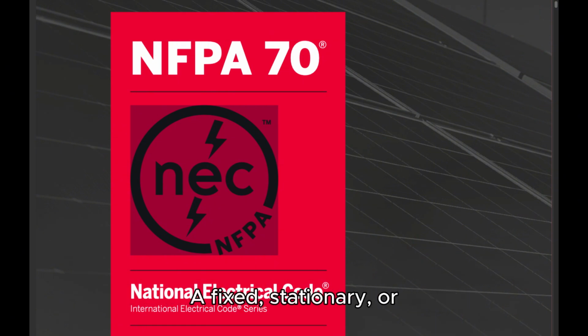CMP13 electric sign. A fixed, stationary, or portable self-contained, electrically operated and/or electrically illuminated utilization equipment with words or symbols designed to convey information or attract attention. CMP18 electric-discharge lighting. Systems of illumination utilizing fluorescent lamps, high-intensity discharge lamps, or neon tubing. CMP18 electrical circuit protective system. A system consisting of components and materials intended for installation as protection for specific electrical wiring systems with respect to the disruption of electrical circuit integrity upon exterior fire exposure.